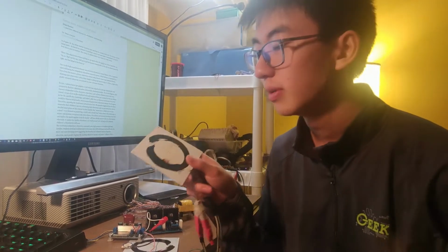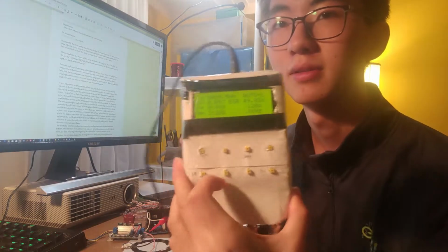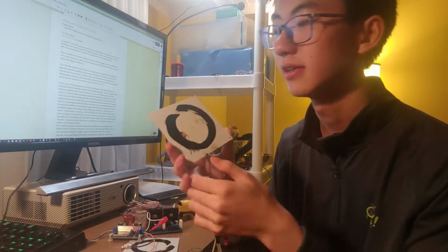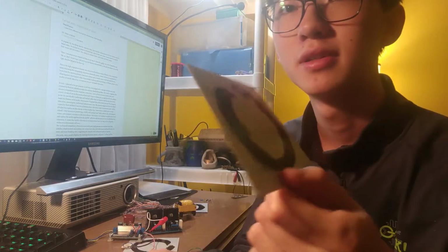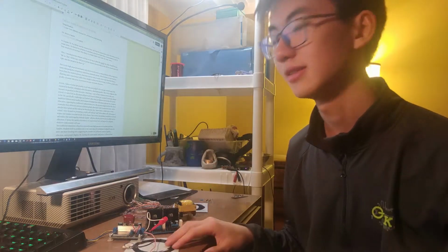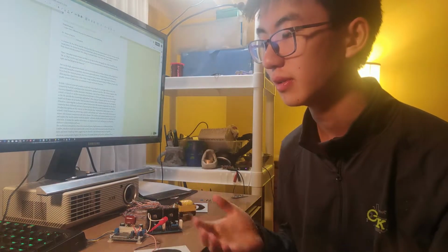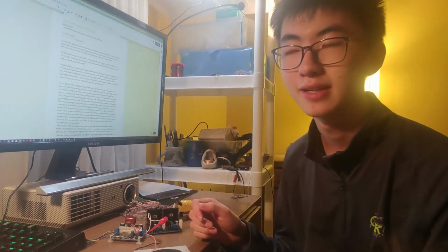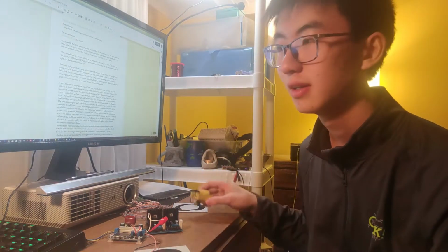The same working principle applies to this piece of coil. As you can see, the readout is at 450 microhenry, which is a lot higher. That's because there are a lot of turns on this board. And it's acting just like a receiver coil, or like the secondary winding on a transformer, except that the core material is air, which is a lot less efficient compared to ferrite or iron powder.